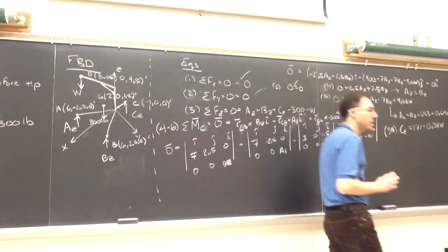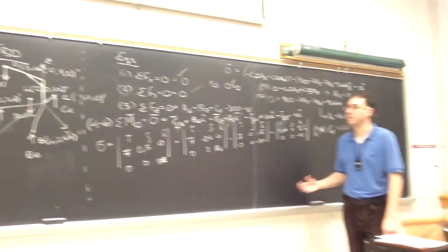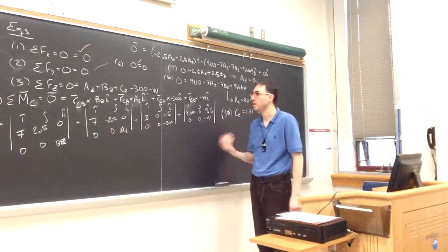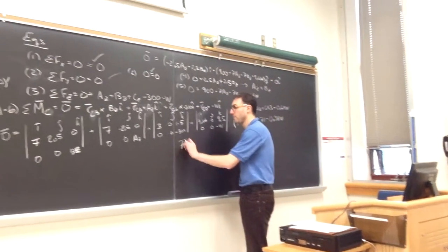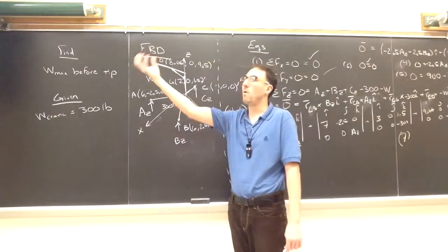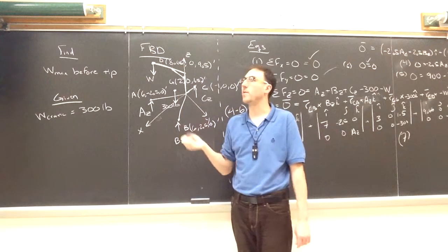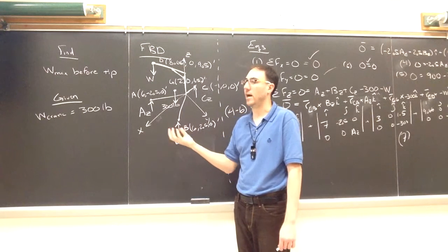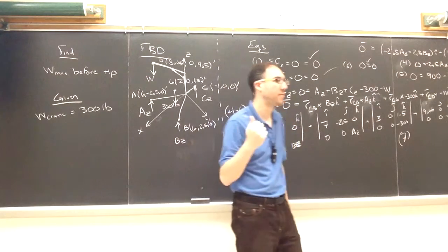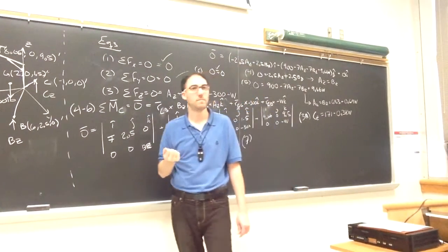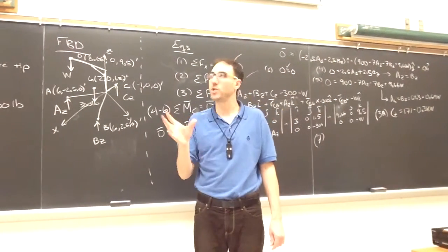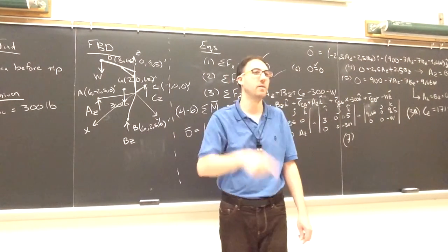But I still need a 4th equation, or I guess in total a 7th equation, in order to solve for my unknowns. So where can I get a 7th equation from? As we add more and more weight to that barrel, what is going to happen with the normal forces we have between the ground and our crane? Right, which one do we expect to go to 0?